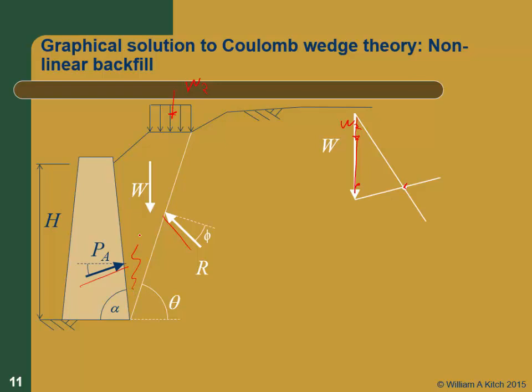And I'll have to use this area to compute A. But if you're doing this on a CAD program, you can just ask it for what the area is. So it's a very convenient method for calculating active earth pressures for arbitrary backfills and arbitrary different loading conditions.